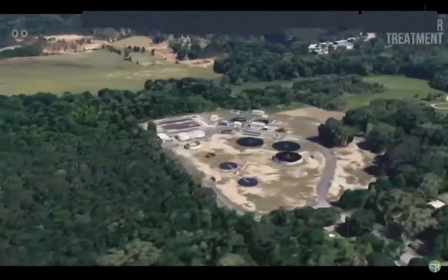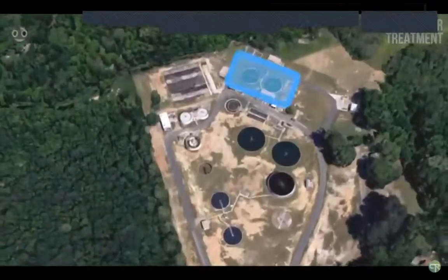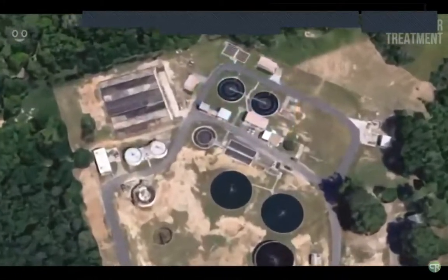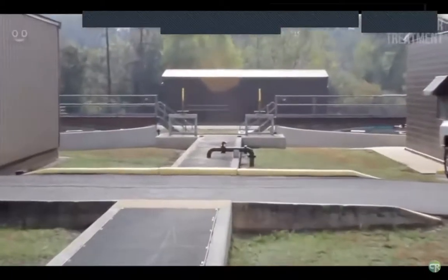Following aeration basins, the effluent along with much of the sludge is pumped into a secondary filter or clarifier, where some of the sludge is removed and pumped back into the aeration basins as the return-activated sludge.